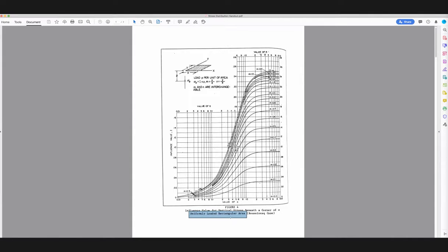And this isn't bad. So this is a nice upgrade from, say, the 2-to-1. And we went through this last time and did an example for both the center of foundation and the corner of the foundation to show you how that compares. And an important takeaway on that is that you establish the loading at the surface, and that remains the same, meaning that stress remains the same.